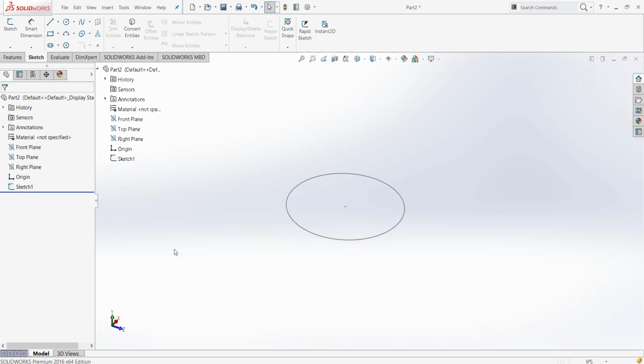By default, whenever you finish your sketch, it's highlighted like this with this light blue, sky blue color, meaning that whatever operation you select next will take into account this selected circle. So I'm going to extrude it into a cylinder. It's already selected. In case it's not, in case you clicked out here and it's gray, if you try to create your extrusion operation, it won't work. You have to select the sketch that you want to work with.